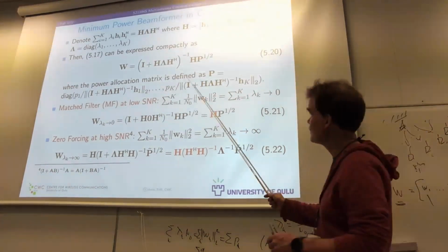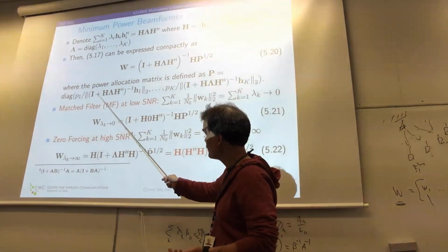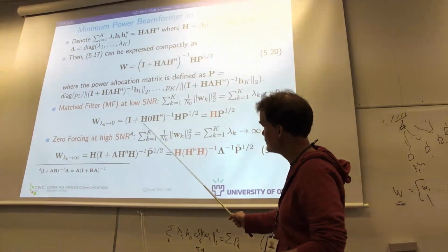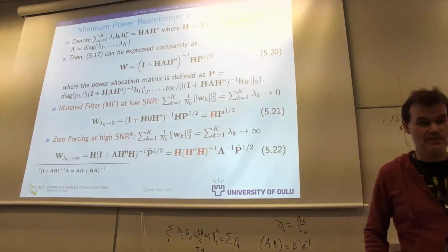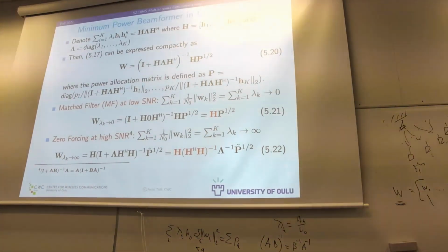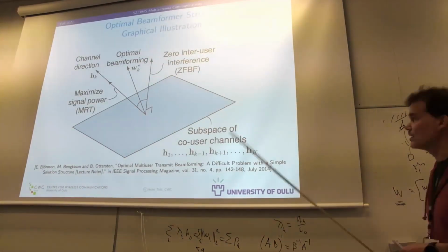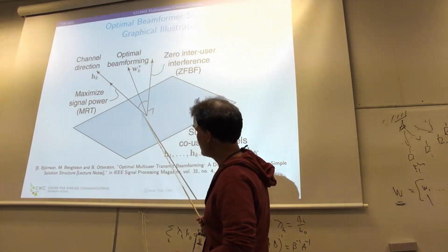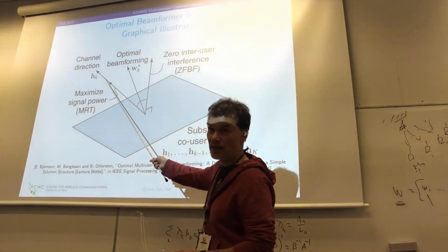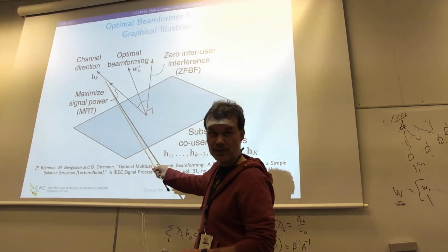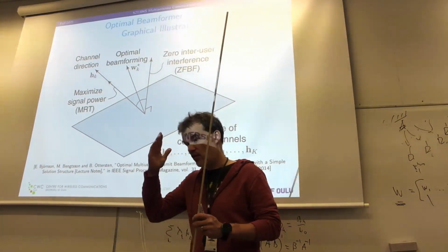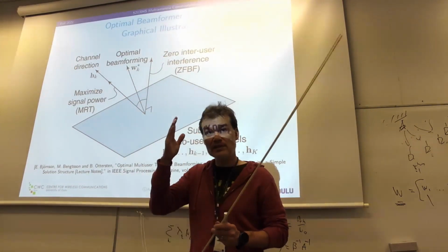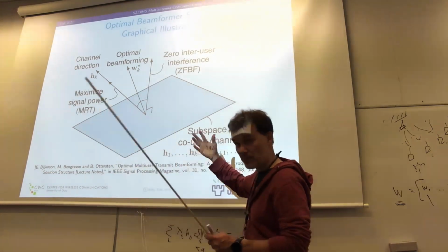But the same thing is just to... Okay, yeah. You have a new definition without this identity here, and basically that's normalizing by the channel for the other case. So this is the graphical interpretation. Again, in the lowest SNR, the beamformer is matched with the channel direction. It's aligned. It's just that your transmit beamformer is just the complex conjugate, the Hermitian transpose of your estimated channel with proper power loading, of course.